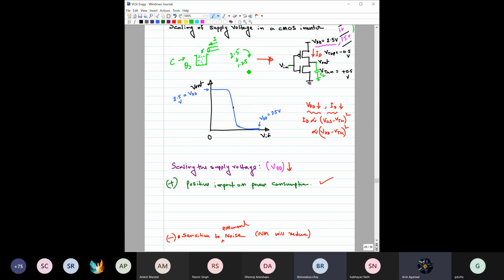Yes, sir. The charge is proportional to voltage. Like, sir, Q is CV, right? So if V decreases, we also require half the charge. So it doesn't affect the charging time, sir. Time constant we take as RC. R and C are not changing here, because C depends on the physical parameters of the capacitor, and they are not changing. Therefore, the time constant should remain the same.